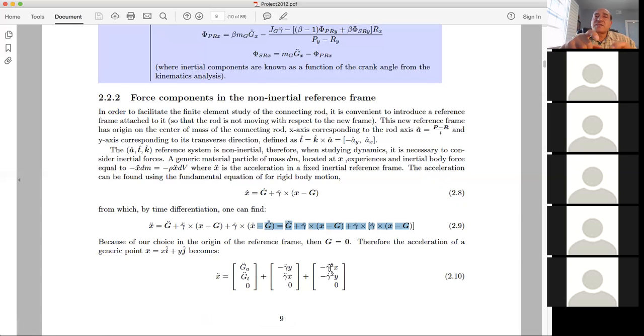So this is like a rigid body. Now the whole connecting rod is assumed to be concentrated at its CG and moving with this x double dot in three-dimensional space, but here actually in two-dimensional space because it doesn't move out of plane. If we multiply the mass times this acceleration, it gives us equivalent body forces.